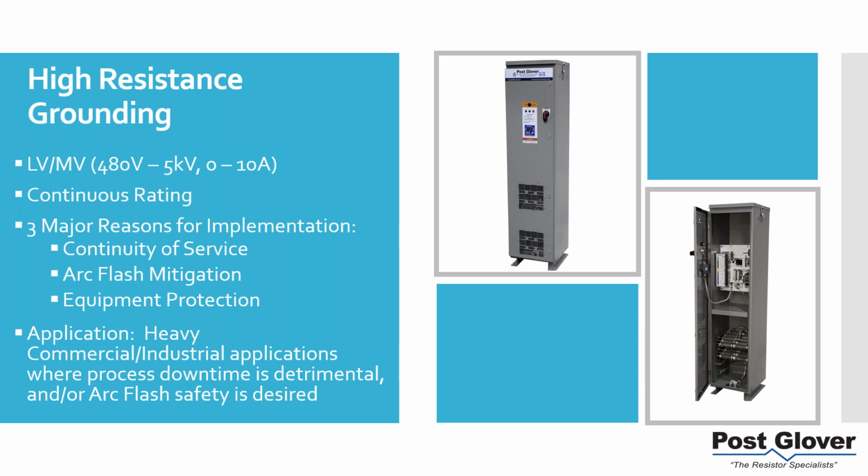Essentially, safely, you can do it up to 5 kV. There's some debate whether or not you can go higher than that, but there is no debate about up to 5 kV. You can use high resistance ground. There are some design considerations. We may go over one or two today, but just know that you can use high resistance ground at that level. IEEE talks about the current range of a high resistance ground as between 0 and 10 amps. Obviously, you can't have 0, but you're going to have somewhere in that range. That constitutes a high resistance ground.